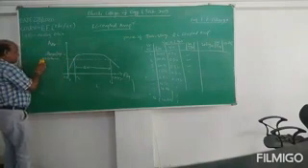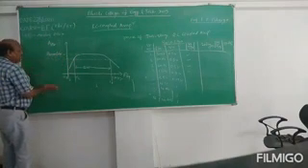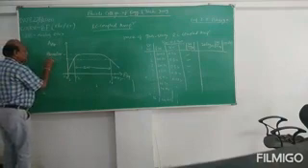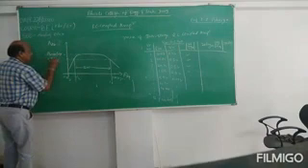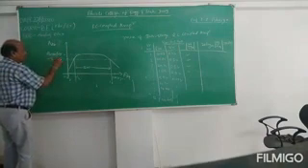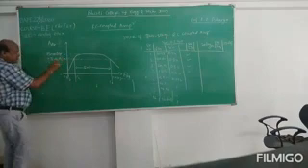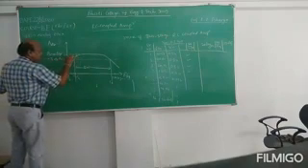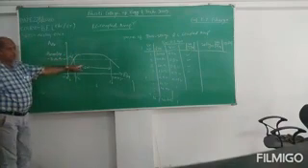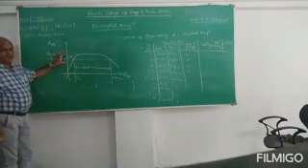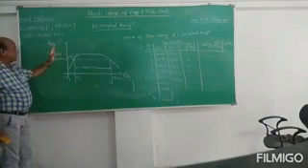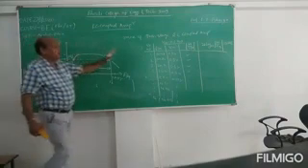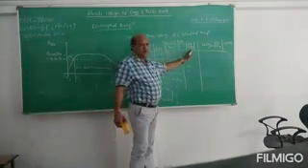And now in place of 0.707, you have to go 3 dB less than this maximum value. So this is minus 3 dB from this A max. In the same graph you will get it here in terms of the decibel. So either you can take the decibel in the vertical axis, or you can take the ratio without any unit.